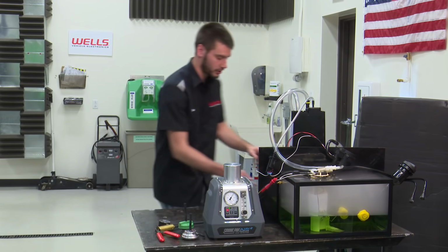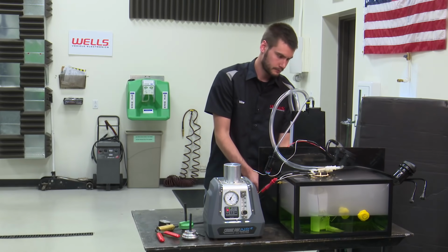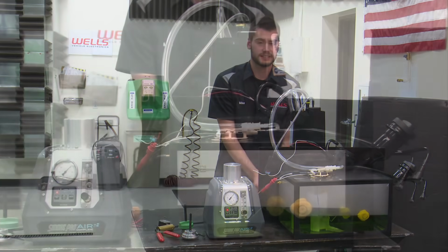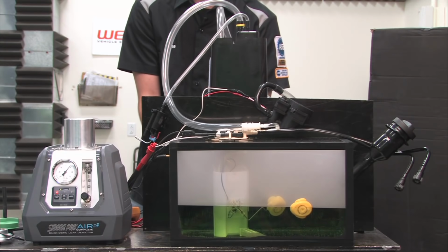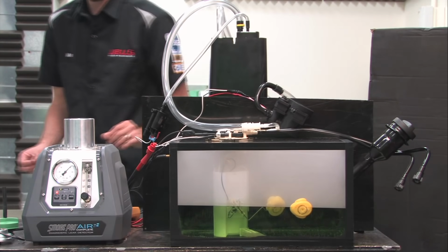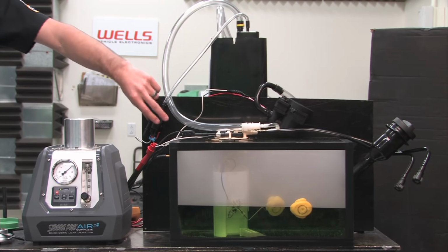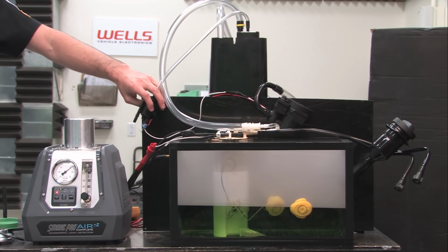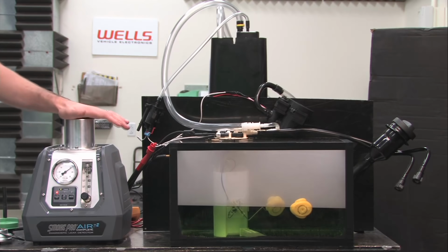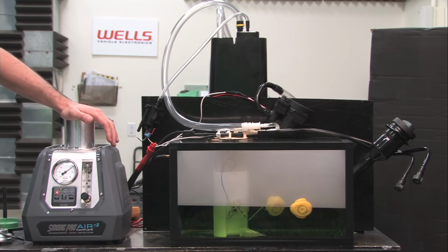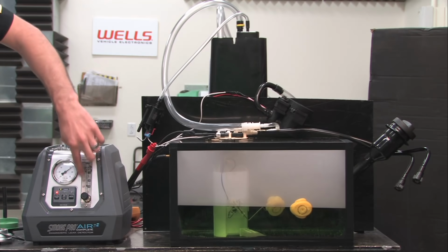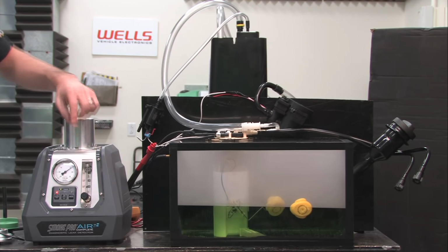So I'm going to go ahead and close up that vent solenoid. And as many of you know, testing vents, you get that click sound. So there we go, that's closed up. And remember, our purge solenoid is normally closed. So right now the system is going to pressurize, and we're going to build up a bunch of pressure in here because I have the vent closed. You can see our needle here is dropping, our ball end here is dropping.